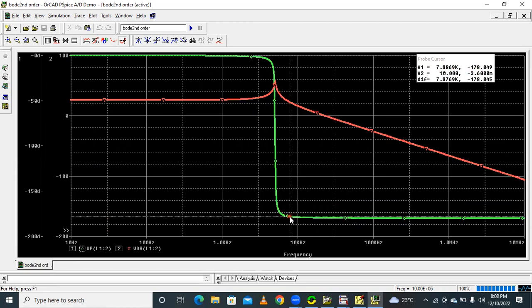That means we require minus 180 degrees, right? So we need the minus 180 degrees line. This line is called minus 180 degrees. Here we get minus 179.962, at approximately 240 kilohertz. This line is called the phase crossover frequency. Understood? So this phase crossover frequency changes.